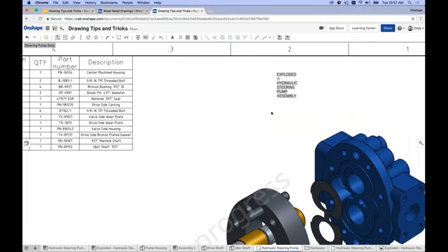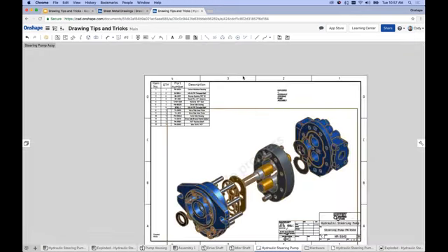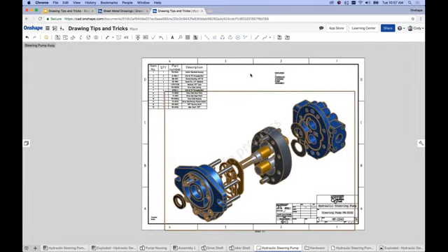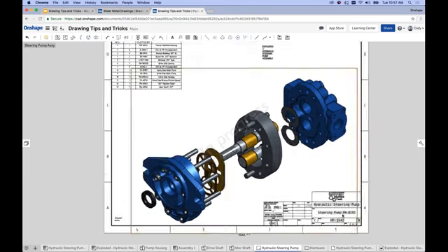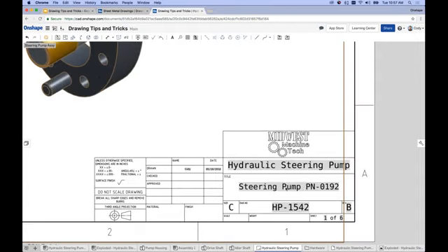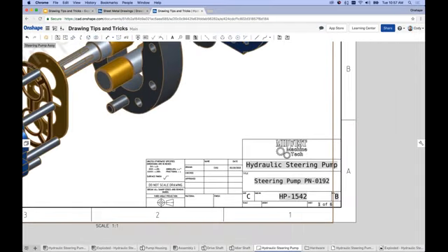All right, so that is inserting notes and linking them more specifically to properties, whether it be sheet reference properties or the drawing properties. That's how you'll get these linked notes that you see in your title block, for example.